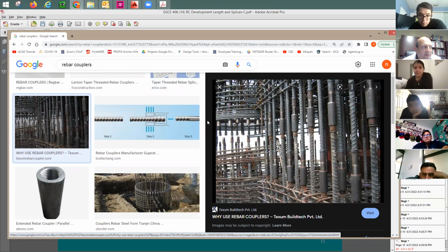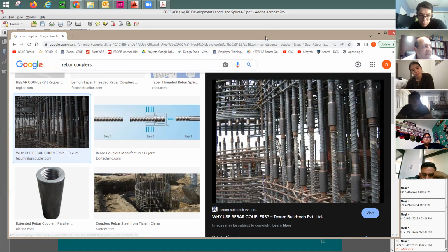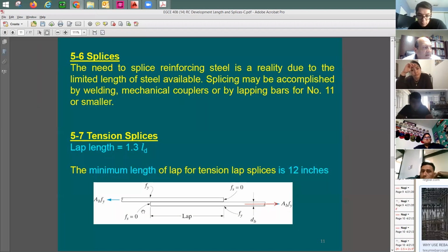I have here a few options. Here's a big circular column, like a spiral column. I'd like to attach this column to the bottom piece of it. So you have the column at the bottom, and you'd like to extend it. If you want to do a splice, like a regular splice, what's the regular splice? I'm gonna say a lap splice, like this. The length of this rebar could be 8 feet or 7 feet, which means 1 story high. This is gonna be too much, right? No one likes this. I mean, this is gonna be kind of crazy.